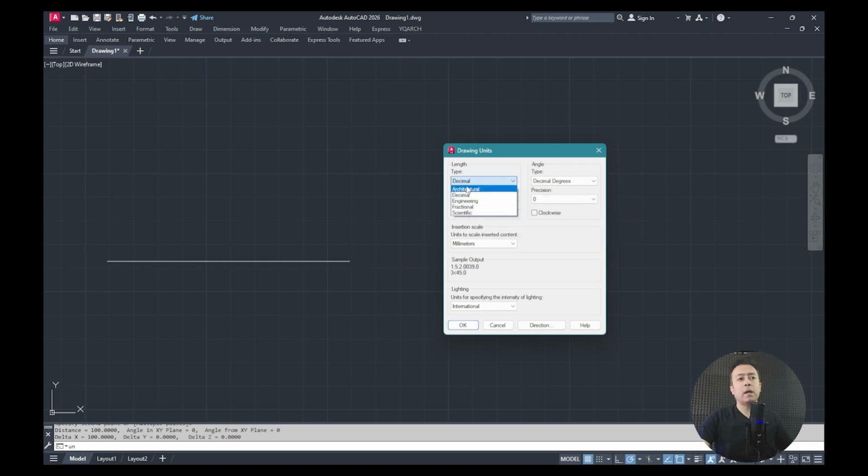This is decimal. Now, there is another different format besides decimal mode. This is also the step after the decimal point. That is, when you take a measurement, now look at this below. All the measurements are given to 4 digits after the decimal point. AutoCAD is adjustable for precision with a maximum of 8 digits after the point. You can adjust this. 4 digits are enough for it.